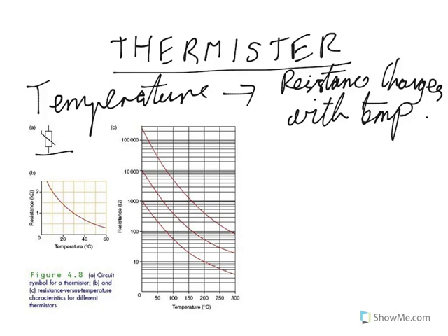So option B, for example, if you have a temperature of 60 degrees down here, then it has a resistance of about 0.4 kilo ohms. However, if the temperature's 10 degrees, then it has a resistance of 2 kilo ohms. So that changes. So thermistors would be used for things like temperature sensors in fridges, ovens, that sort of stuff.